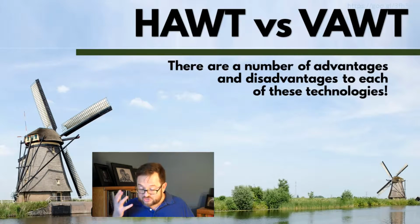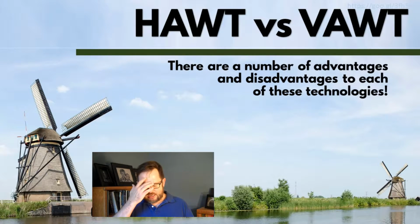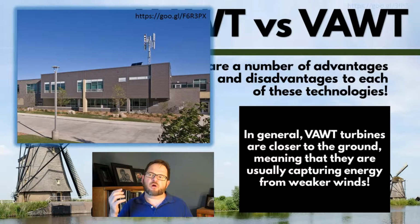But just to be clear, there's a lot of different pros and cons, or advantages and disadvantages, to using HAWT versus VAWT in different situations. There is no single answer, like one is always better. It has to do with the application. Broadly speaking, though, VAWT turbines are generally going to be closer to the ground, and so they are generally experiencing weaker winds.